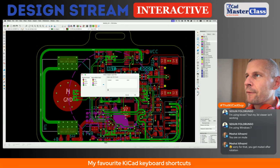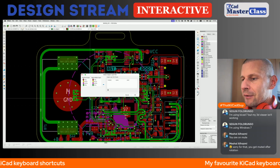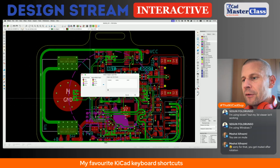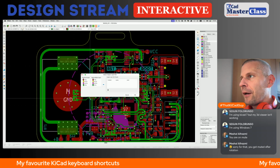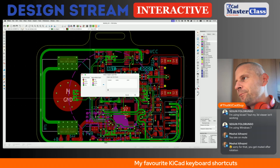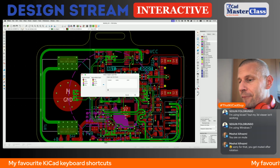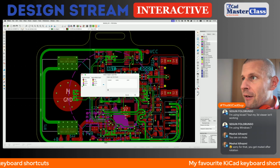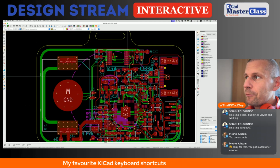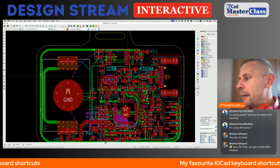top and bottom. For instance, when we are routing a multi-layer board like 6, 8, 10 or more, and you are working on inner layers adjacent to the reference plane, and you want to use, for instance, buried vias, and you want to switch between the inner layers, you can define another pair, and then you will switch between these newly defined layers in a pair.